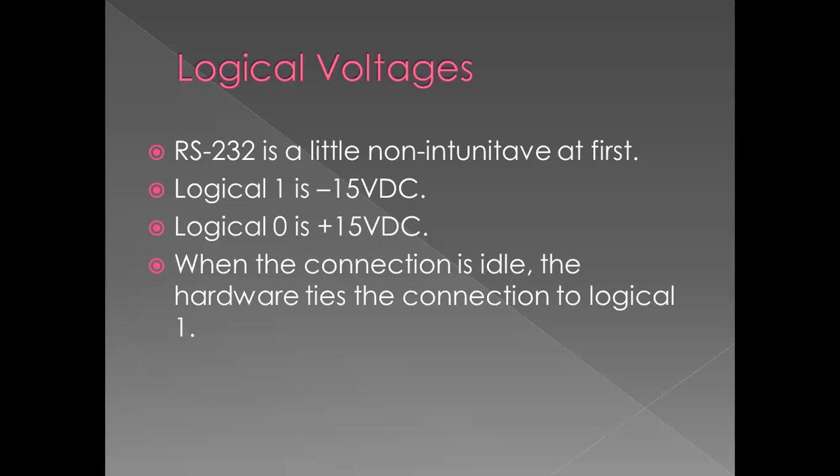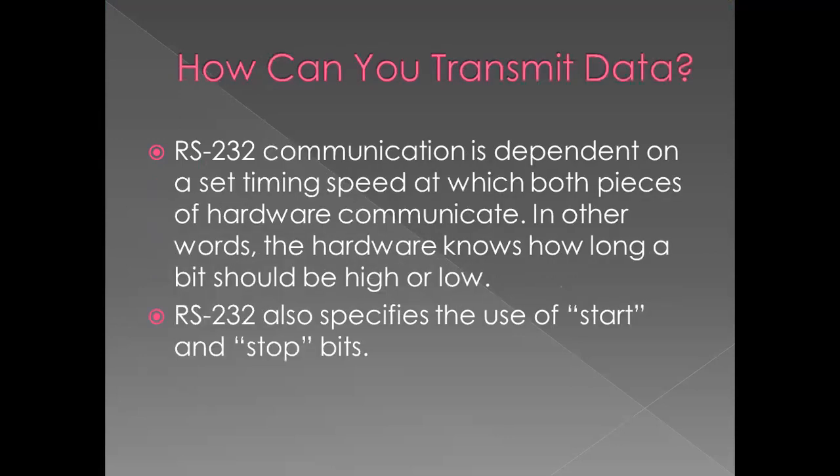Logical voltage. RS-232 is a little non-intuitive at first. Logic 1 is at minus 15 volts. Logic 0 is at plus 15 volts DC. When the connection is idle, the hardware ties the connection to logical 1.